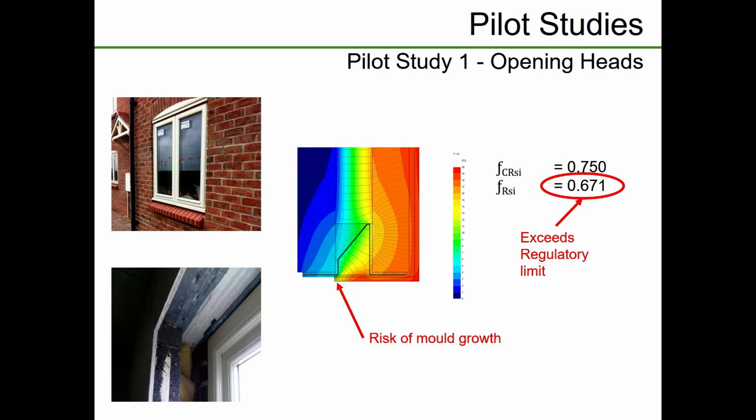Whilst on site, we had a look at this and we could see condensation forming on that steel. Okay, so there's an interstitial condensation risk as well in that junction, sort of around here. Okay, so they will have problems.